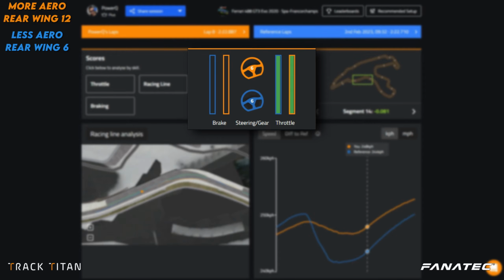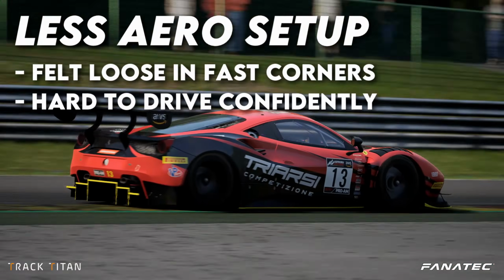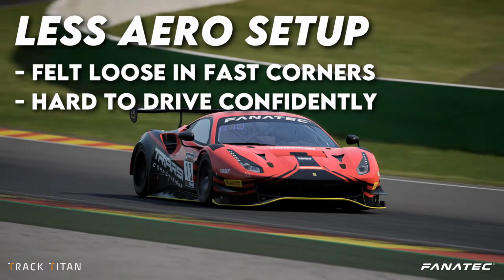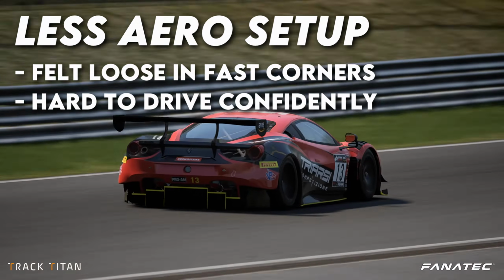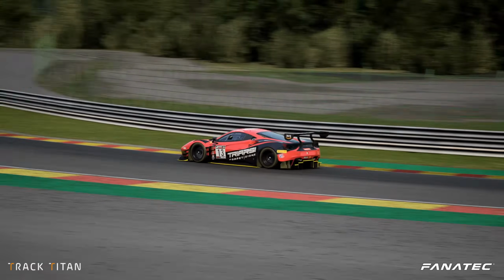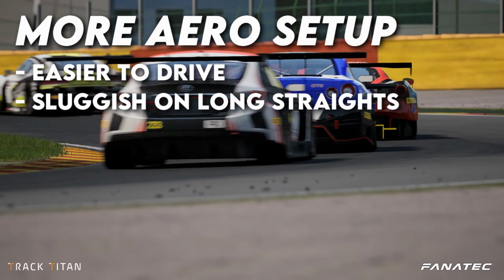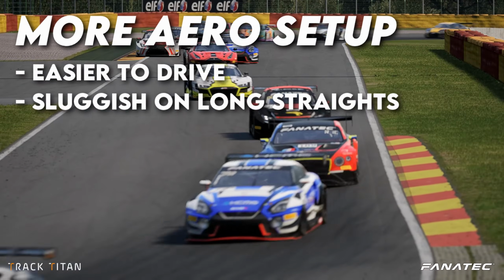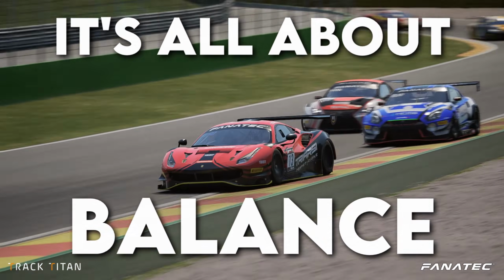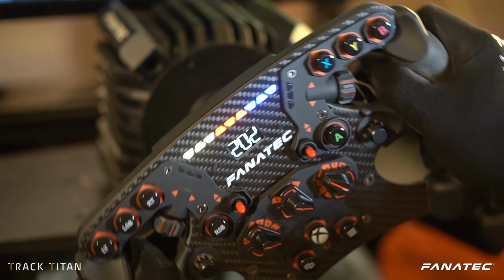So the main difference in driving these two aero setups was that the car with a very little rear wing felt very loose during the faster corners and was prone to oversteer, making it a lot harder to push to its limits with a lot of confidence. While the more aero heavy car was easier to drive, it did feel sluggish in the acceleration on the longer straights. So, as we've said before, finding a good balance between the two is key. And that's a great point to round out the video on.